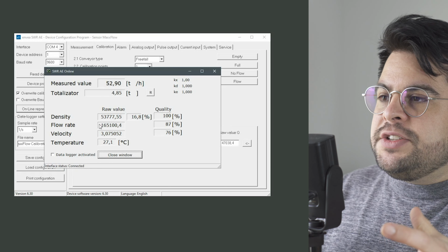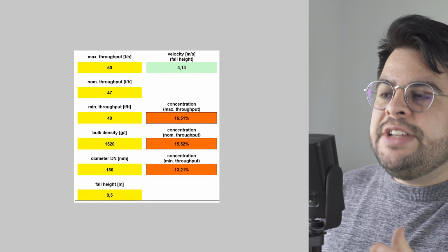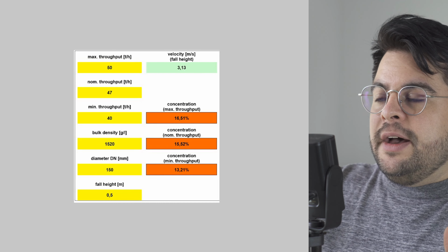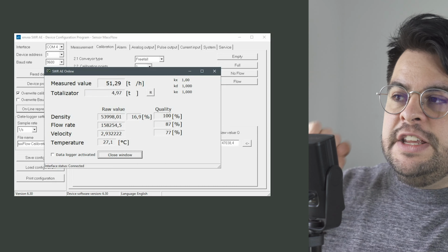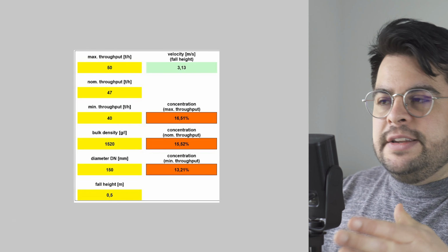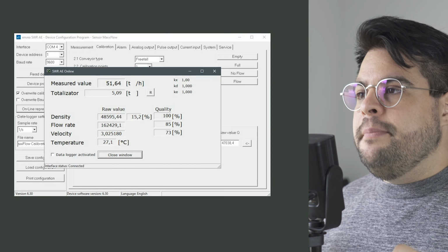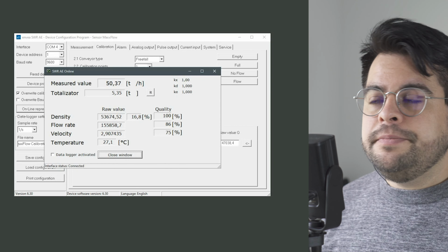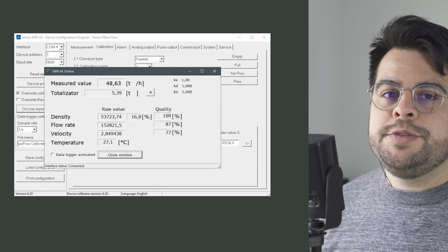You see, when the sensor density information reaches 16% occupied, the mass flow measurement goes to 50 tons an hour. This is what's showing there. How much is occupied, the density information, and the measured value. It stays a safe application, and a pretty good sensor response. And that's it. It's pretty much it. We basically place the sensor there, start recording data with a nominal flow rate, create an average of the stored data, write in the sensor again, and write the mass flow information.